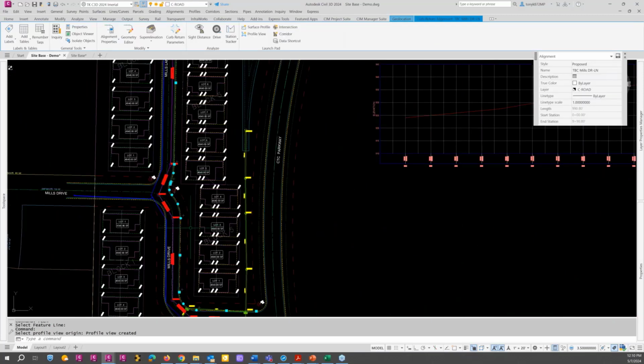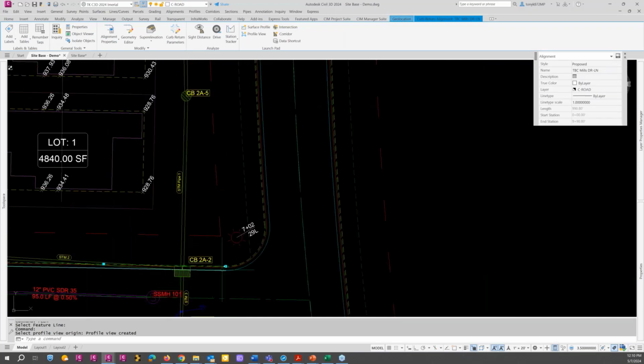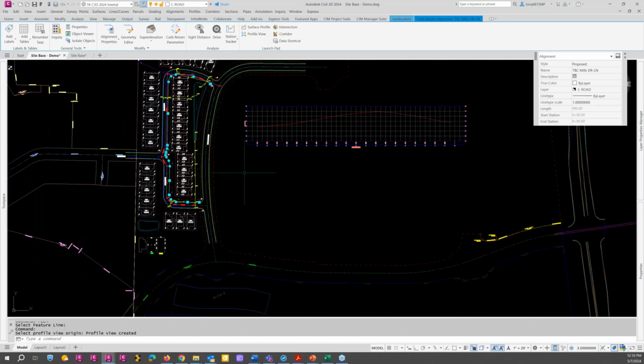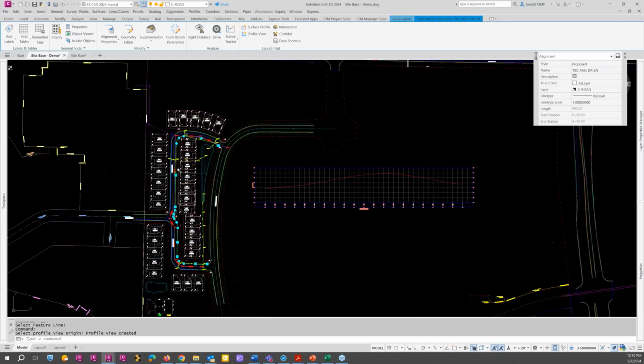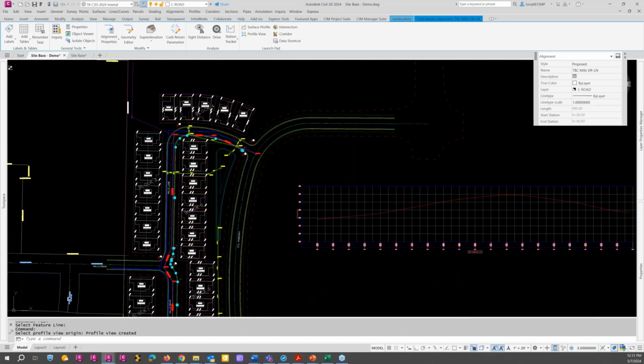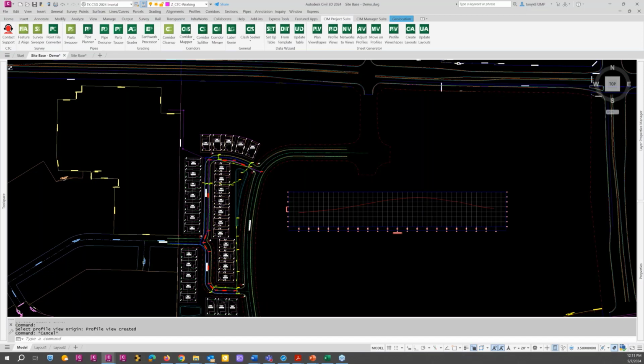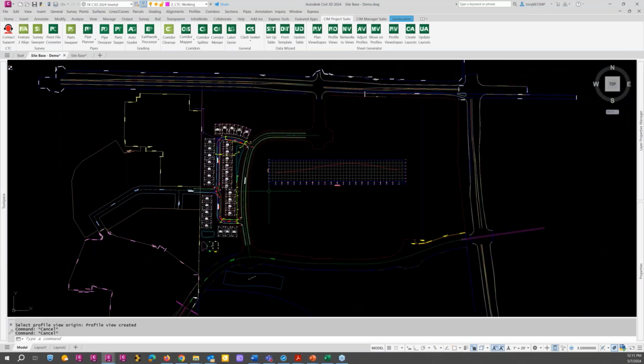That runs the entire length. So now we have this whole curb here, and with the profile we have vertical data, so we can export that, as I said before, as XML or RXL, Trimble format, however you do things. So just that quick, we can get that ready to go stake.